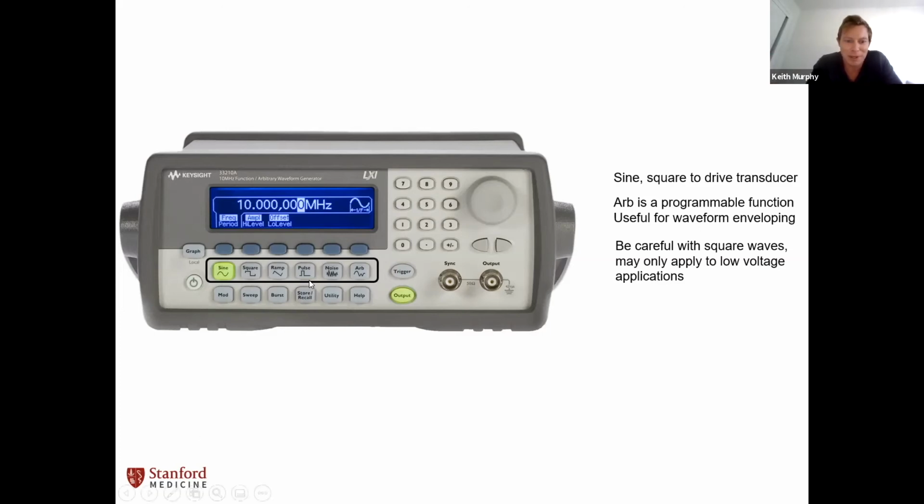Kim, do you ever use the pulse or ramp function on a function generator? No, I think for fundamental frequency, it's always just a sine wave. Yeah, so you can probably skip over these, and you can even skip over noise. These are probably more for radio frequency research. But another thing we commonly use in ultrasound research is the arbitrary function button or waveform.